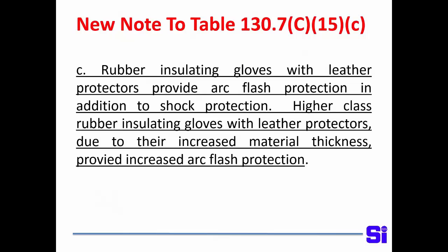We're putting a new note to Table 130.7(C)(15)(C): rubber insulating gloves with leather protectors provide arc flash protection in addition to shock protection. I run into this all the time where people think that arc-rated gloves provide shock protection. Arc-rated gloves provide protection from the thermal effects of an arc flash only.